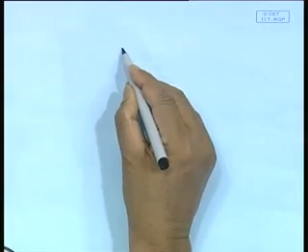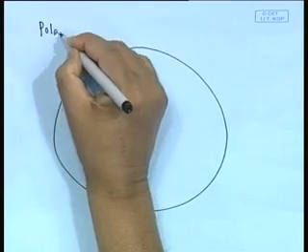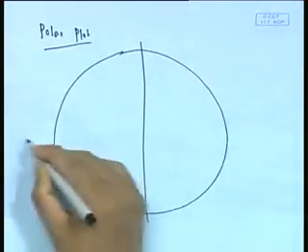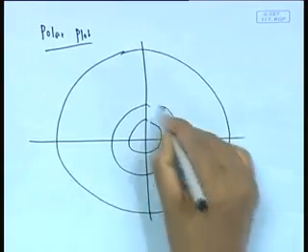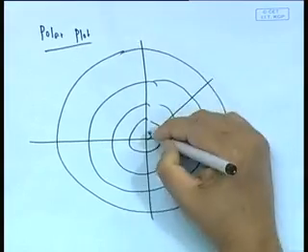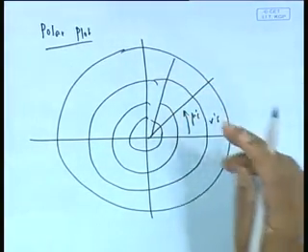Then having done that, one makes what is called a polar plot. That is the most interesting thing. So, you will calculate for various sea states. For different sea states, one will calculate all these criteria. For example, you find out how many times slam occurs. Then we make a polar plot. Now, polar plot looks like that. There is a circle here for order of merit. So, we have here various speeds. Actually, it is a radial plot of V versus theta. So, these are various V's and these are various mu's or headings. Okay.